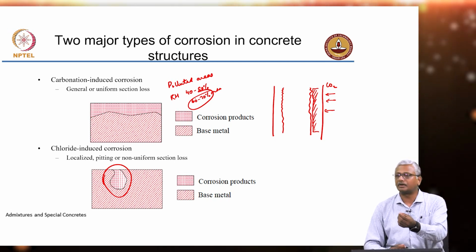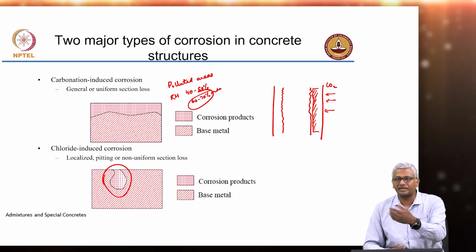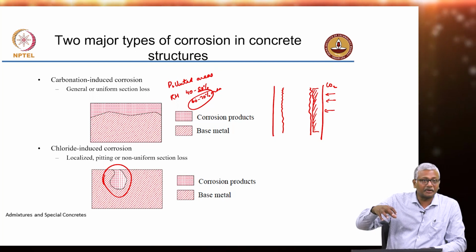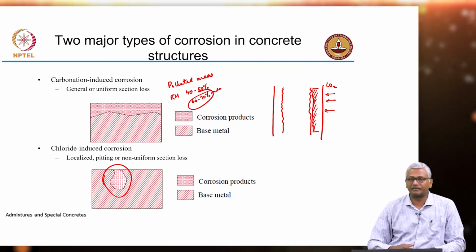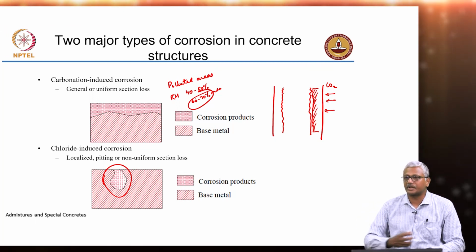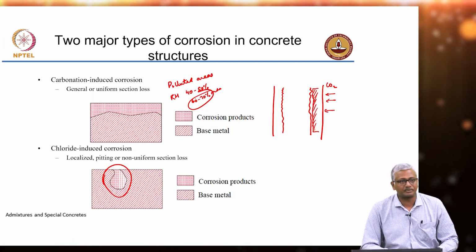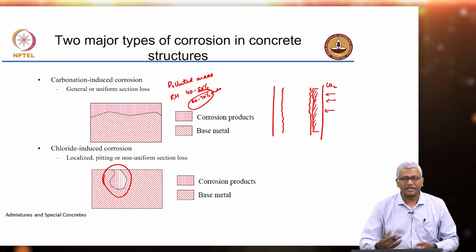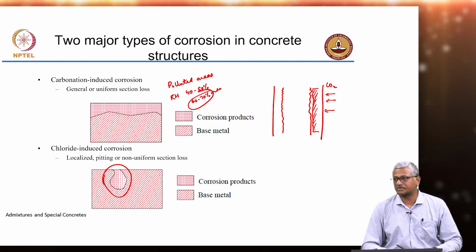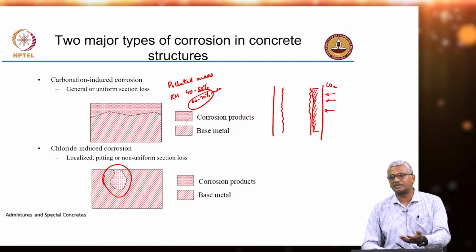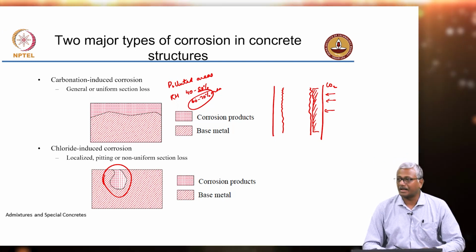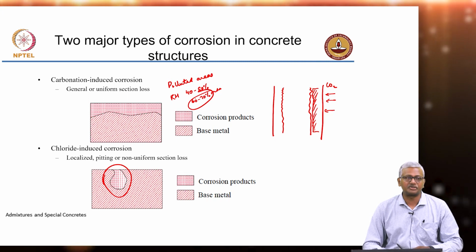Like your small polythene covers and all, if they make their way into the composting yard, they get burnt, and this microplastics will release chloride, there is chloride available in the system, and that also adds to the load of chloride in the soil. It combines with the water or dissolves in the water and is available for corrosion of the steel. So you would never imagine that chlorides would be present in a place like Delhi, but yes, groundwater there has fairly high chlorides in some regions.